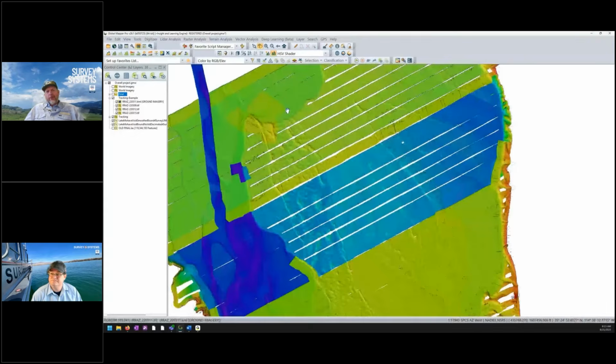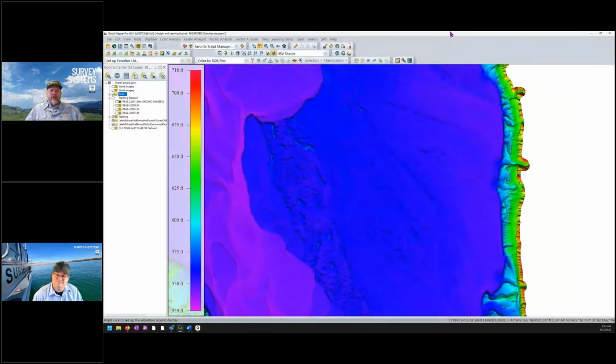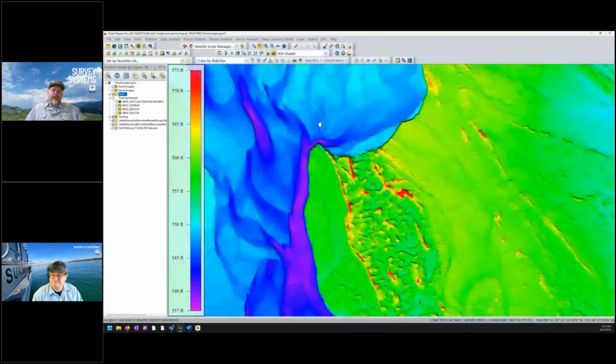And the huge benefit of using it is you can translate the data and send it back and forth. So our data collection package does not do coordinate transformations, and so those transformations have to be handled outside of our data collection package. Once you set your data collection up, you're stuck with it. You can't drag in anything like you can in Global Mapper and it'll change the coordinates if it's in the header. It doesn't do that.